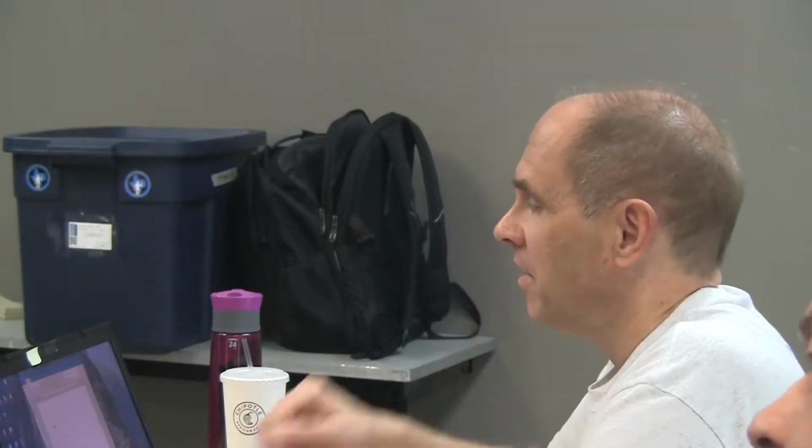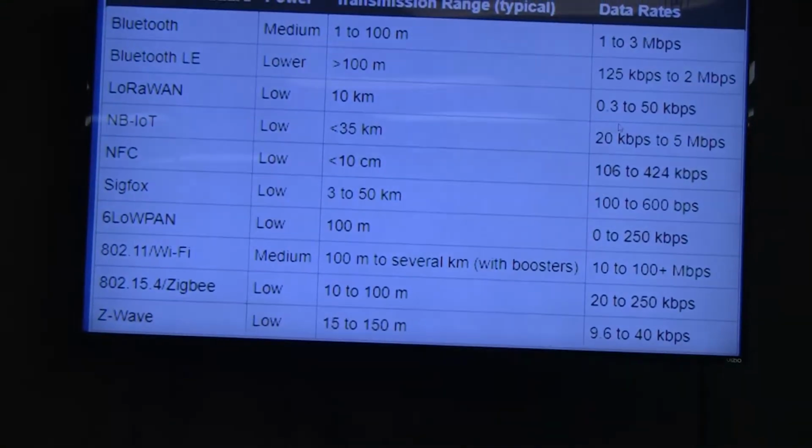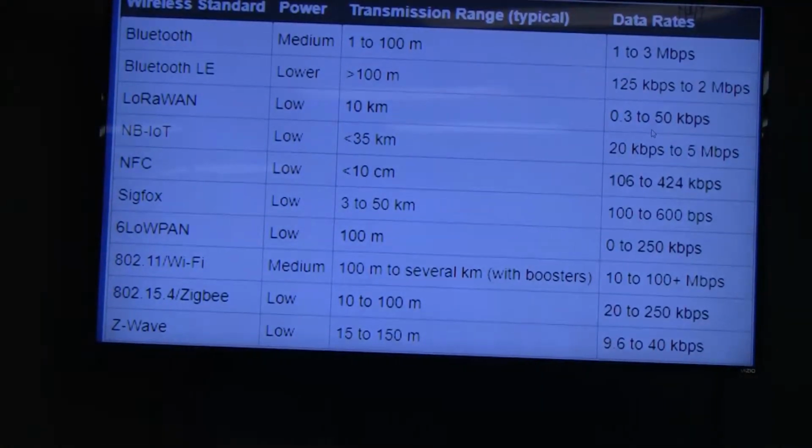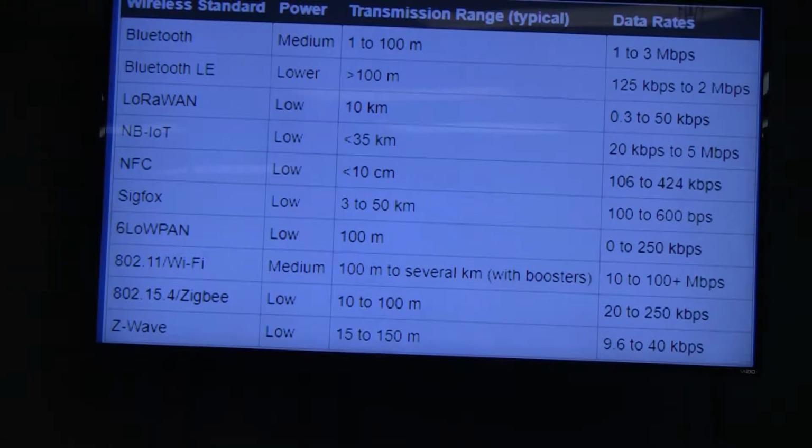So what's the common name for the 802.15 series? Is there one? Well, XBee is XBee. No, Zigbee is the most popular variant that complies with it, but there are a lot of other ones. Okay. Where was LoRa fitting? LoRa would be on this lower end because it's low power, very low throughput. You cannot transfer very much data over that. But for most applications, unless you're streaming audio, I haven't encountered anything in my professional work that requires anywhere even near the top of this data rate.